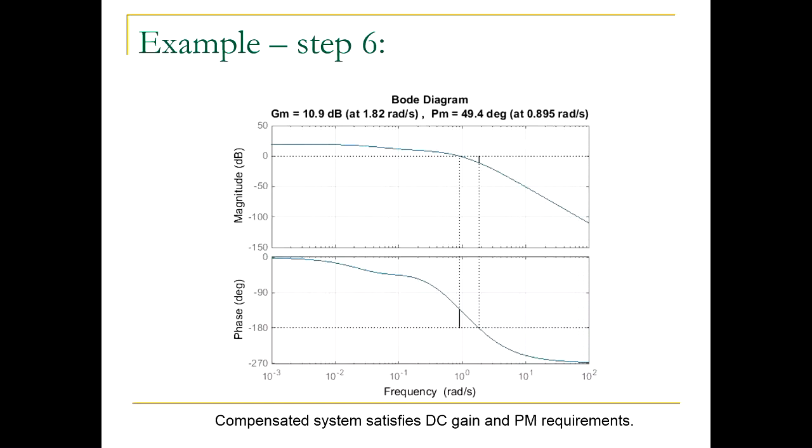And note that the gain is at the right spot, because in the end, after all the steps, we managed to maintain the gain required for steady state error. We moved the crossover frequency to the left. At that frequency, we had more phase margin, and the lag was added at lower frequency, where we had excess of phase. So note this dip.